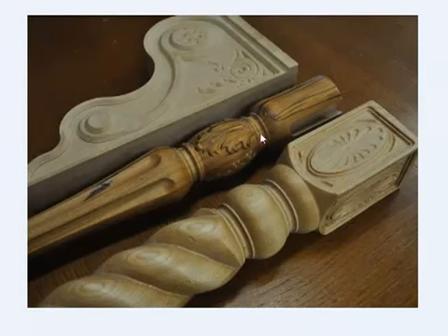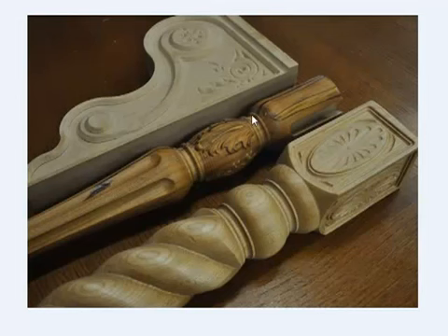This middle spindle, for example, used Aspire to create this wrapped carving. It used Conversational CAM 4 to do the turnings and the toolpaths for here, and then I also wrote a little G-code to cut the dovetail slots on the end. So I was able to combine all of the programs created by the various software packages into one code and let it run.